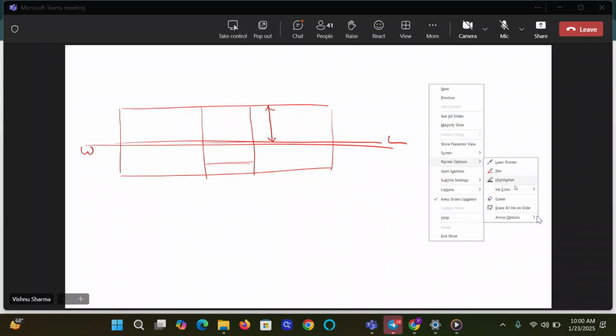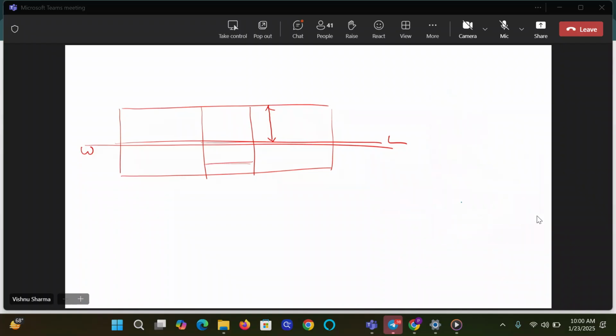But now suppose there is a watertight flat instead of here, or it can be in addition to it. Suppose there is a watertight flat here. Let us say draft is 6 meters or whatever it is, and let us say there is a watertight flat at a height of 6.5 meters. Now, the watertight flat is above the intact water line and reasonably close to it.